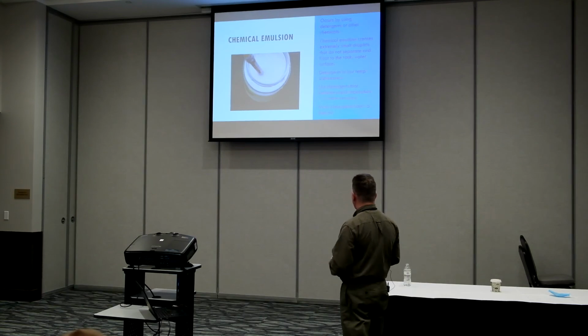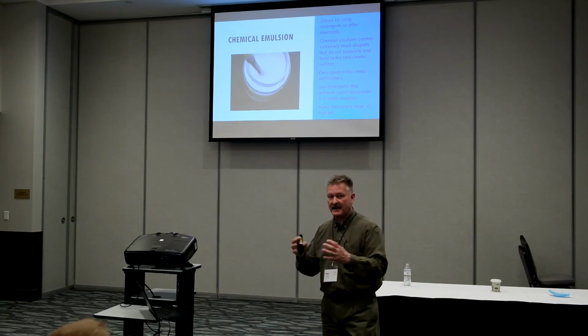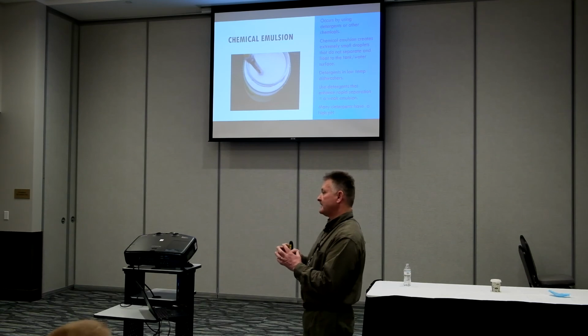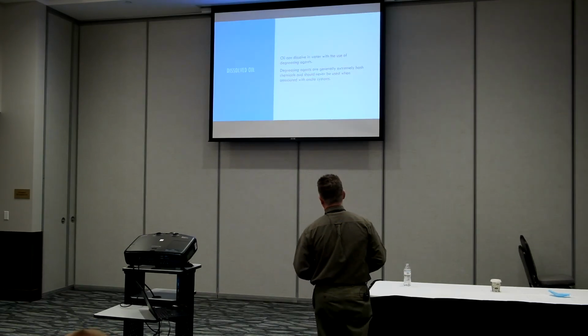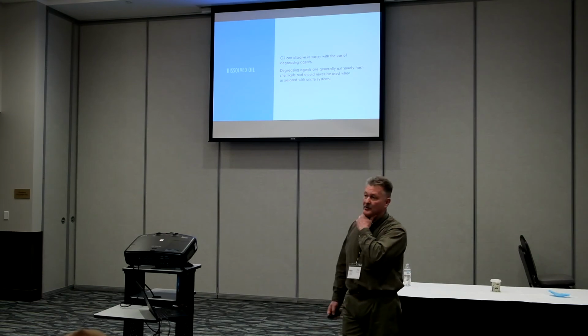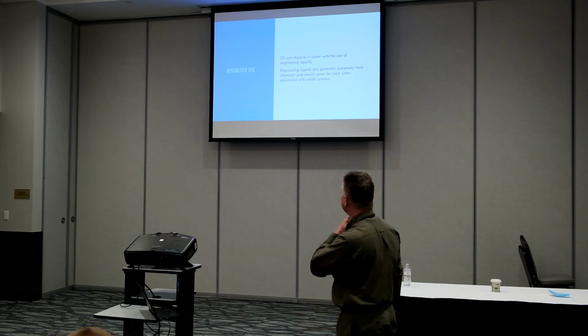So if they do have that, they want to make sure that they use detergents that enhance a rapid separation, meaning it's got a very weak emulsification. There are detergents that they can apply that will help minimize this potential. Dissolved oil, usually those are very harsh degreasers, chlorinated solvents and so forth. So we definitely don't want that in our systems.